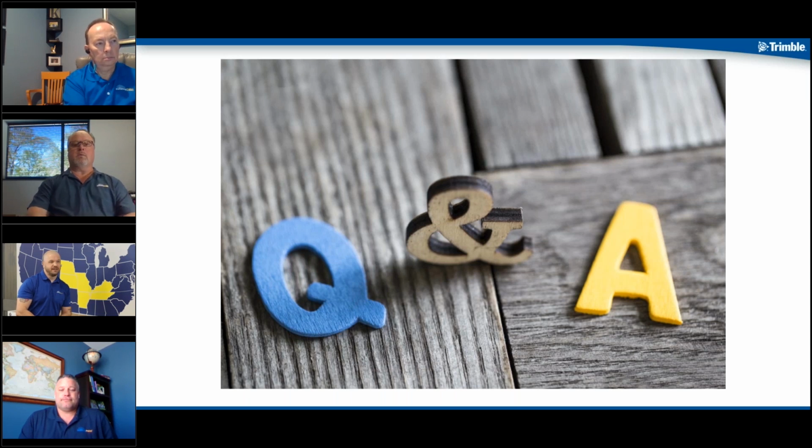To reiterate, the other part was just how do you know which control point was off? And you pretty well covered that by saying go back and back shoot those. Once you're set up, shoot to that control point and then shoot to the next one. Sam, that was one of your questions, how do you verify? The way that I've done it in the past, when I know there's an anomaly or something's off, is you get your setup done and then you shoot back to the others, and it's going to tell you which one's off. And then you can flag it from that point.